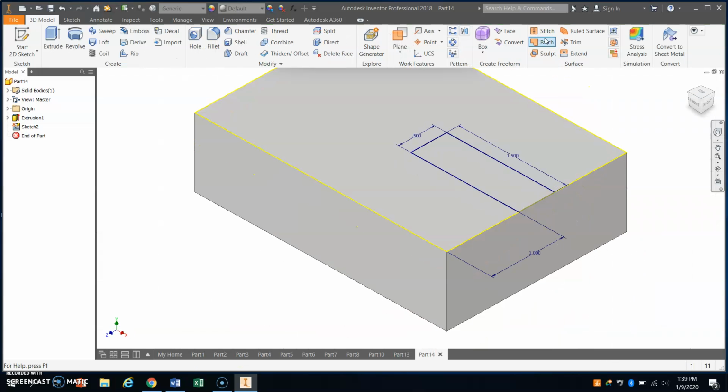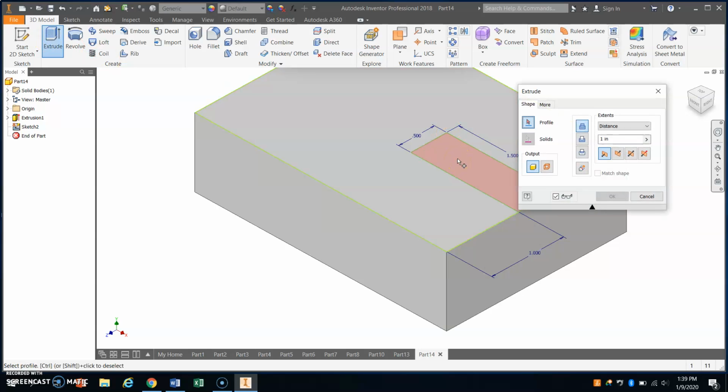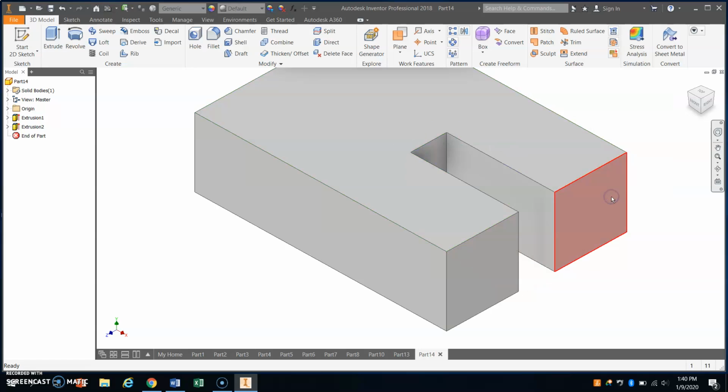Finish sketch. All right, so I'm going to see if I can extrude this. But instead of extruding it, I'm going to cut it. And as we talked in the last video, instead of going at the distance of 1, which appears to be good, if I discover later that this is too thin, that I need to thicken it up, I want that to automatically transfer so I don't have to go back and redo that extrusion as well. So if I do all, then it will take me all the way through to the bottom.